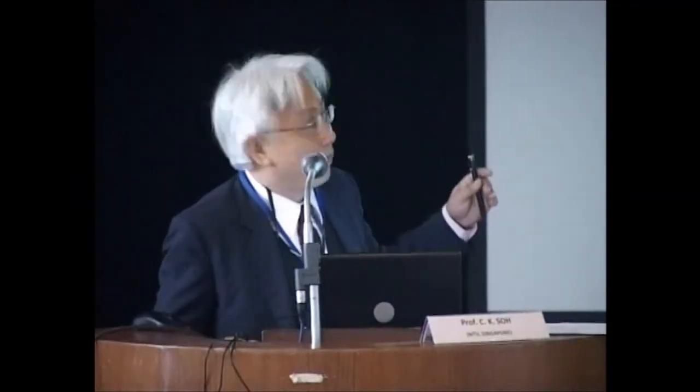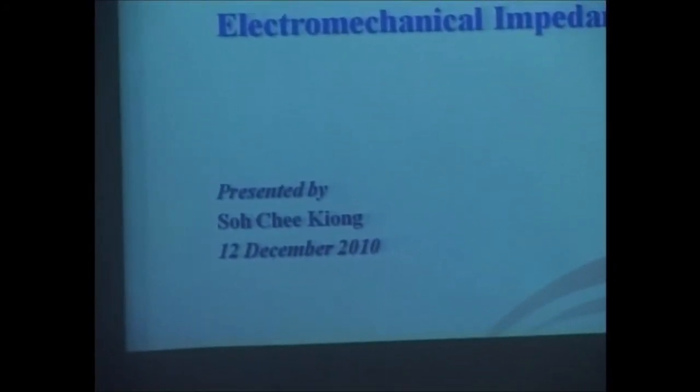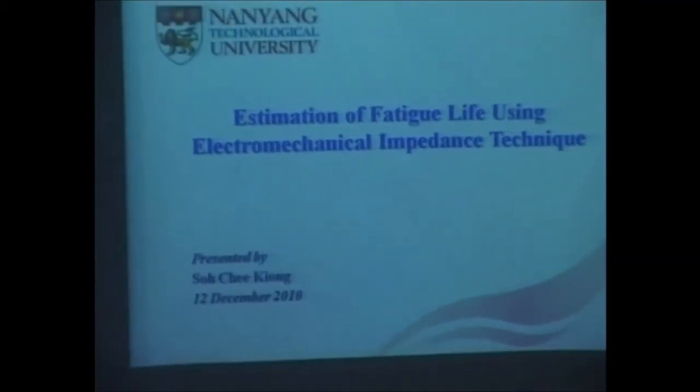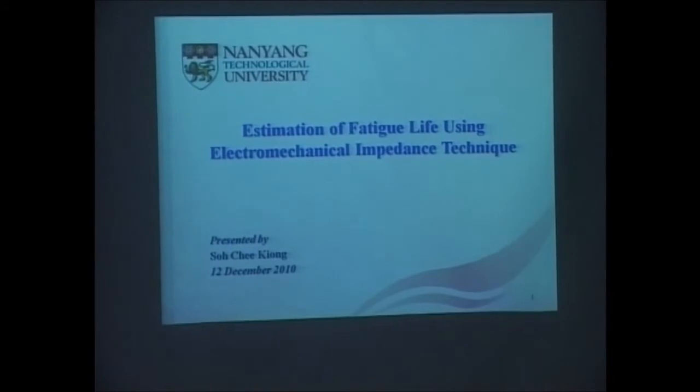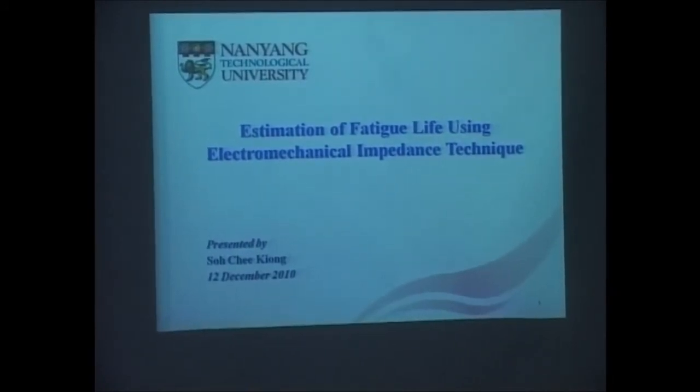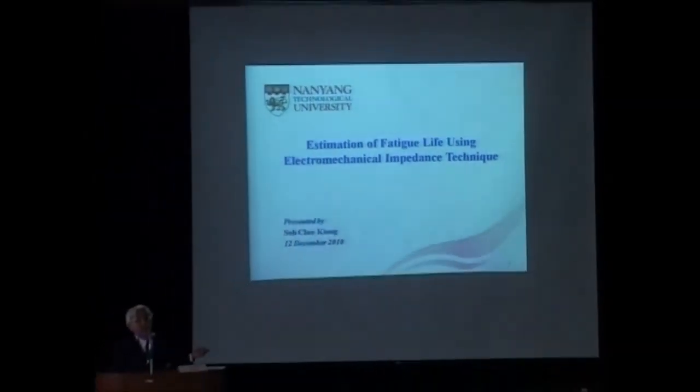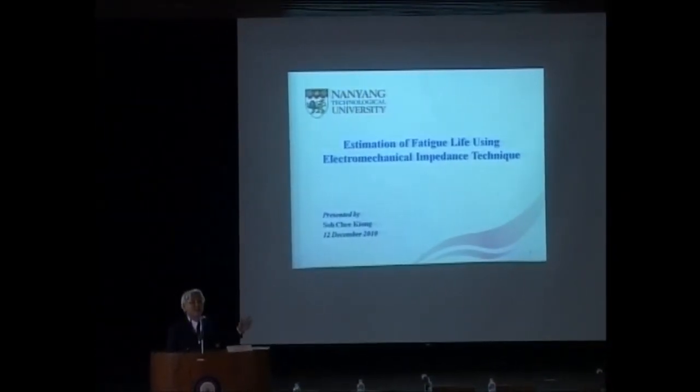Okay, what I'm describing is that we have moved from structural health monitoring to damage prognosis. We want to predict the remaining life of the structures. After monitoring, after knowing they have damage, what are you going to do about it? Not every damage should be repaired. My first job was with McDermott, on offshore structures. We usually design for 25 years. So if you happen to have found a brace drop off after corrosion, fatigue, do you want to repair it? If it's designed for 25 years, it's already serviced for 20 years. If it can stand for another 5 years, then let it service for another 5 years. Don't waste your money and time.